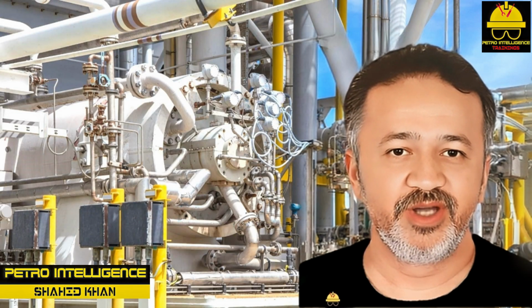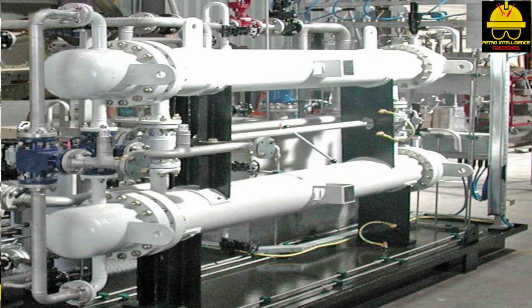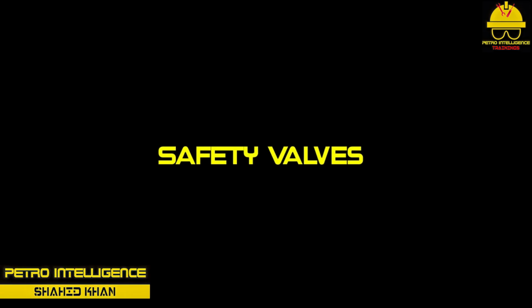Intercooler and aftercooler heat exchangers. The compression of gases creates heat in a compressor. Shell and tube heat exchangers, intercoolers and aftercoolers have been added to the design to control high temperatures. As gas is discharged out of the first stage of a compressor, the intercooler lowers the temperature. This cooled gas is directed into the suction line of the second stage compressor. As this gas is compressed, creating more heat, it is discharged into the aftercooler before going to the receiver.